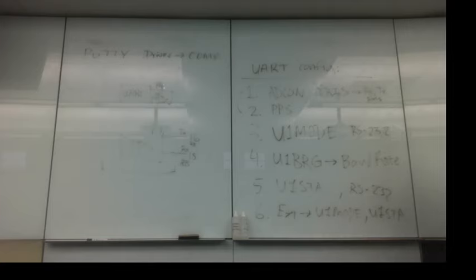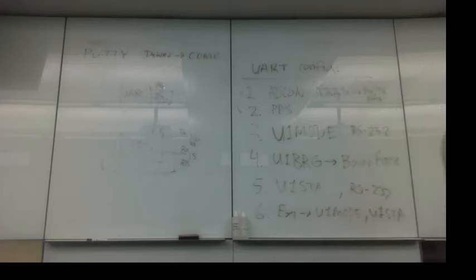So if our instruction clock is 16 megahertz, or 16 million instructions per second, then the top one will divide it by 16, so we'll just get a factor of 1. The bottom one will divide it by 4, so we'll get a factor of 4. Okay, so here's, to me, the most important part. It doesn't really matter if you're in high speed or low speed mode. The max that you can do is 4 million baud, in high speed mode.